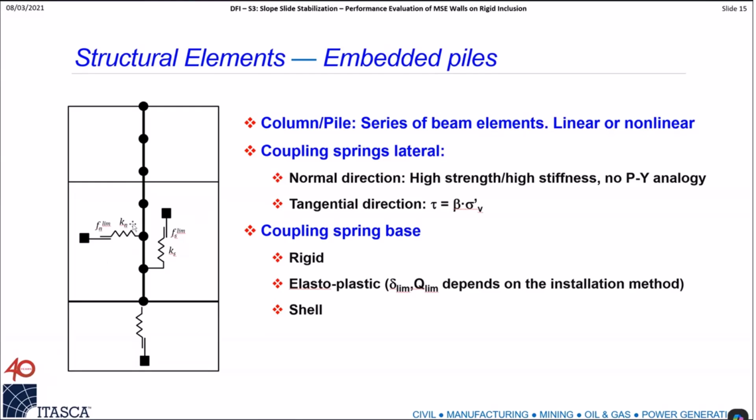And these links, this connection creates so much confusion that is unbelievable to a certain extent, because it's very simple. These are not PY curves, okay? When we use LPile or any kind of program of that sort, the soil is not present. The PY curve or the T-zeta curve is essentially the soil, right? It simulates the interaction with our structure, with the soil, and everything that comes from the soil is essentially lumped into the coupling spring, right? So if you have a sand, you have a certain formulation that is developed. If it is a clay, a hard clay, or soft clay, there are different shapes and so on that can be used to determine what kind of PY curve you need to use for those types of analysis.